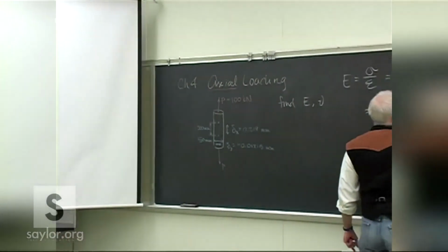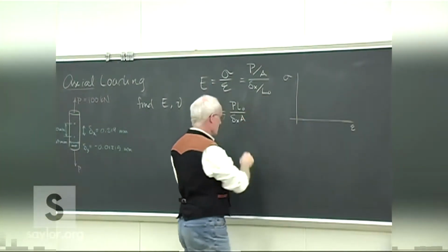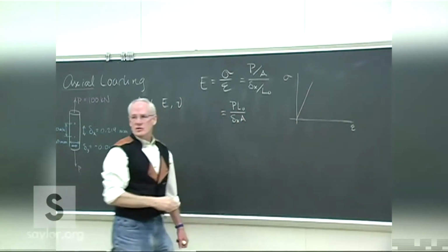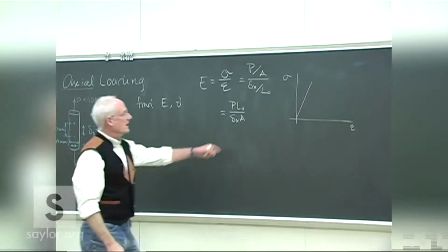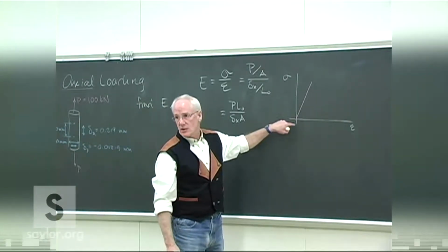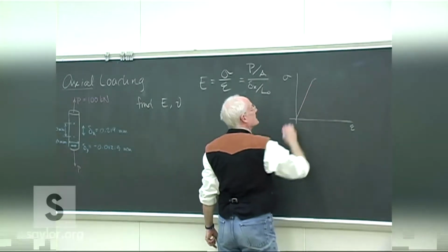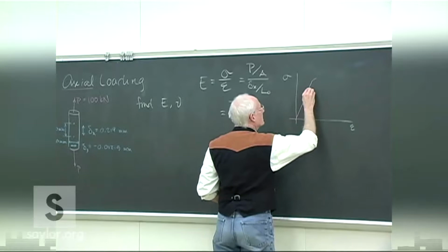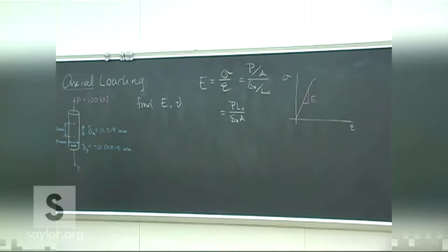Remember this stress-strain relation, and especially this elastic modulus region. We're most interested for our design purposes in that linear region, the elastic region, where if the load is relieved, then the strain is also relieved. If there's any residual strain, it's because we've gone past the proportional limit somewhat. And we're most interested in this linear section. It's that slope that actually is the modulus of elasticity.